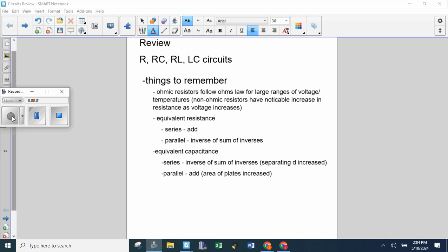When we do circuits, it's got to be the RC circuit. Right? You've got to know how to go through the entire process of doing the charge on an RC circuit, doing the voltage on the resistor, doing the voltage on the capacitor, doing the current in the system, but you also know what to expect. Like from t equals 0 and t equals infinity, you know what to expect.